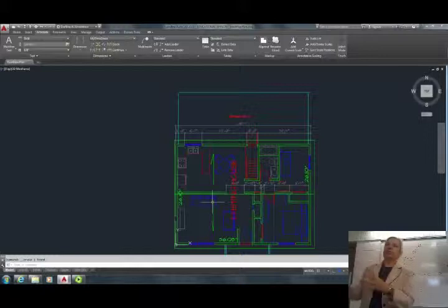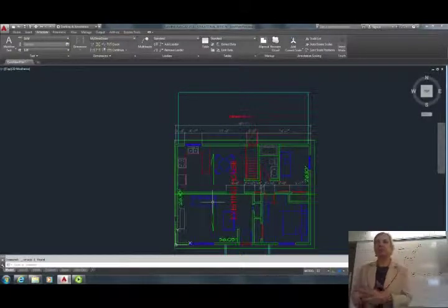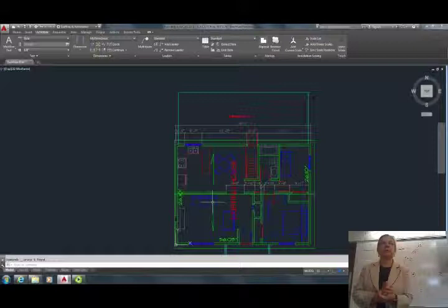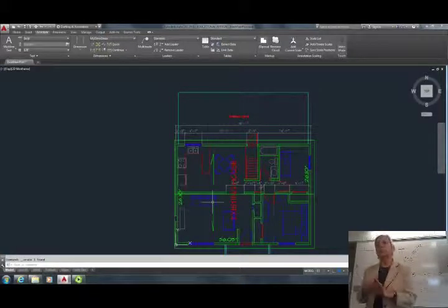Now, having said that, you draw the wall either 4 inch or 5 inch because the 4 inch stud is actually smaller, and the half-inch drywall could be the smaller drywall, whatever the contract specifies further. Our drawings are not actually specifying what drywall the contractor has to use, so if they use the 5/8, 5/8 is bigger than half-inch. If they use 3/8, then the wall size changes. So that's why I always want it to be safe.